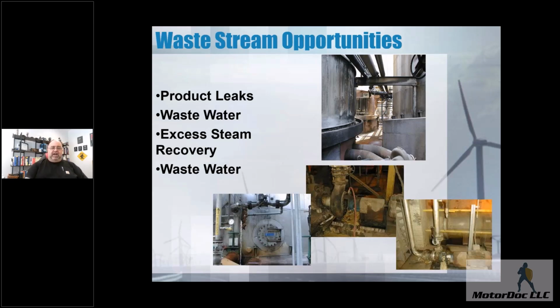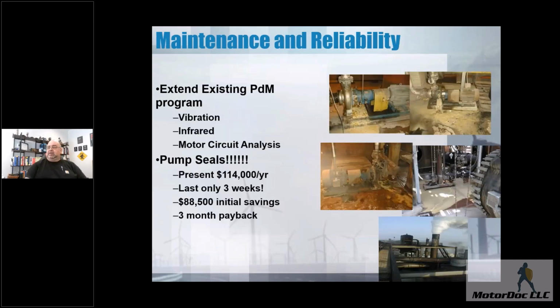So that was a significant find, and our recommendation was go back to the double lip seals so that they can be replaced. And then we had a seal company come in to look at what would fit that application better. So here's more examples of that. Yeah, they last only 3 weeks. To replace all of them was an 80. That was their cost if they had been replacing them. But everywhere we went, there were leaks.